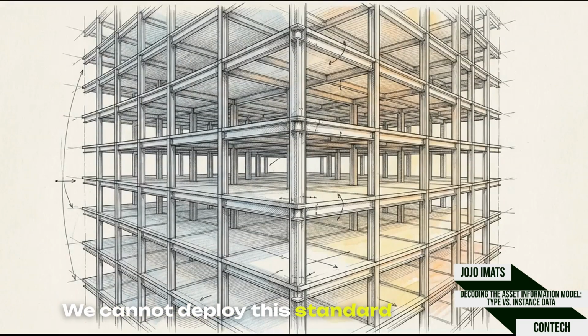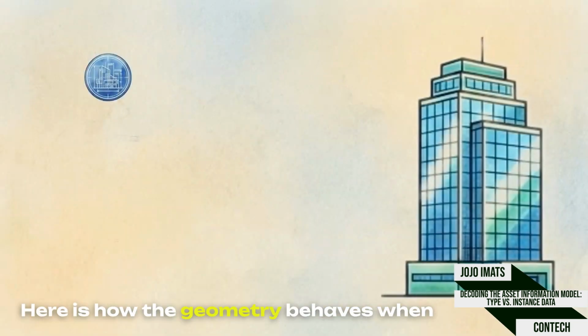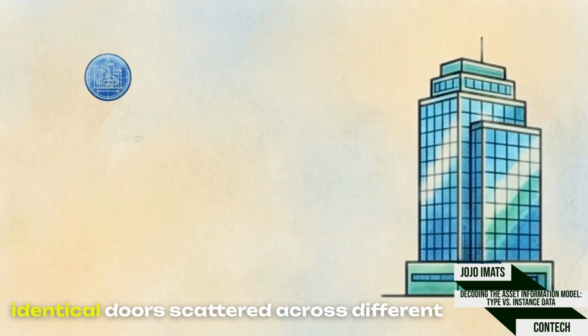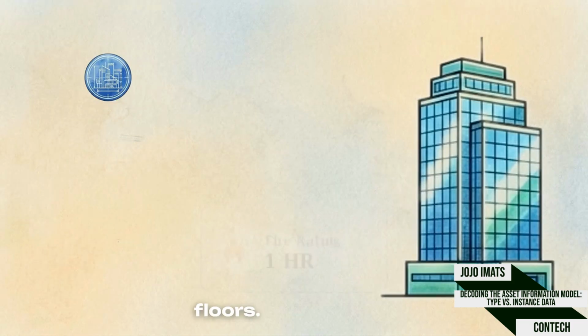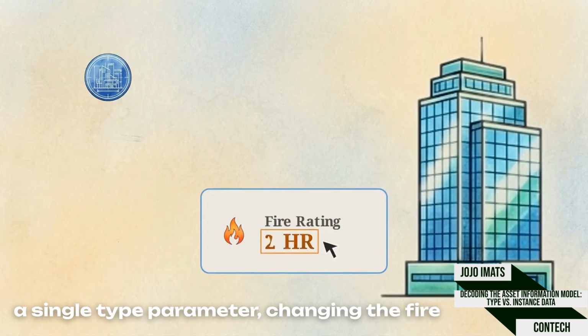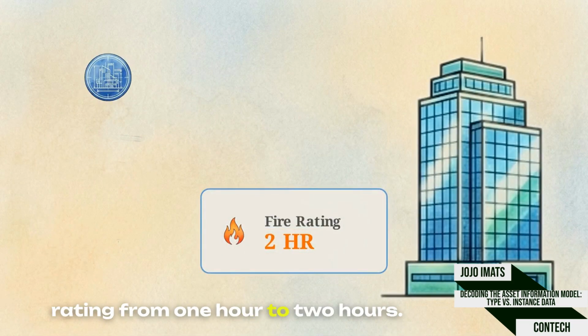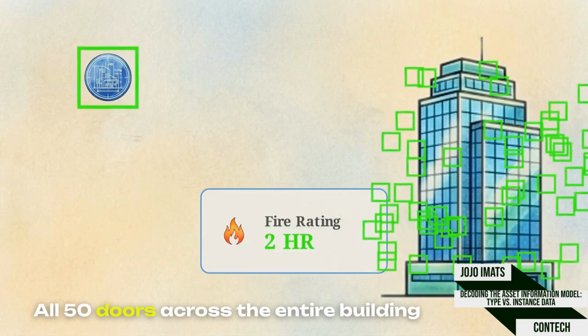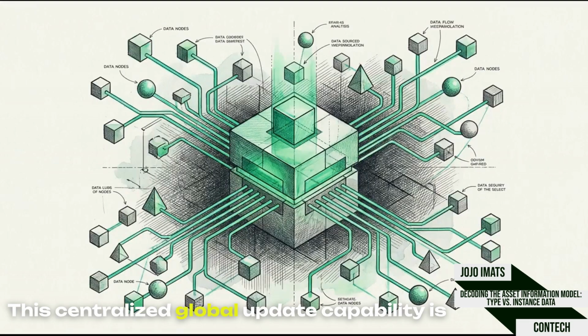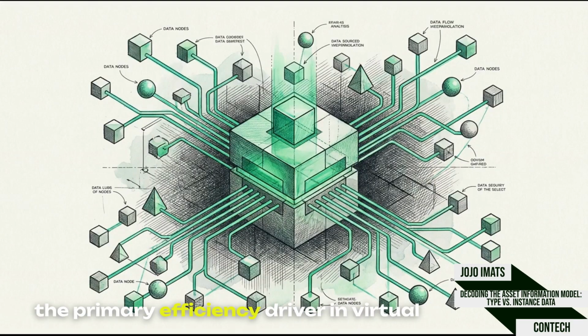We can deploy this standard component across a large-scale project. Here is how the geometry behaves when we multiply that single fire door into 50 identical doors scattered across different floors. Watch what happens when a user updates a single type parameter, changing the fire rating from 1 hour to 2 hours. All 50 doors across the entire building instantly reflect this new data simultaneously. This centralized global update capability is the primary efficiency driver in virtual design and construction.